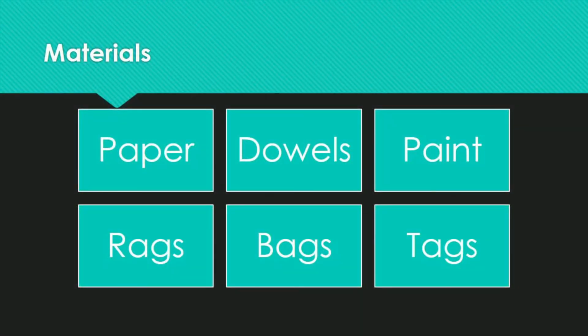And lastly, let us look at materials. So for materials, there are 6 major materials that you should be aware of. Well, the first one is the craft paper with the polyethylene backing. And of course, this is used as a bandage to cover exterior paste after it has been brushed onto the pole. You also need wood or plastic dowels, which are used for sealing holes after poles have been treated internally. You also need pole marker paint, which is used to identify which poles need to be replaced or stubbed.